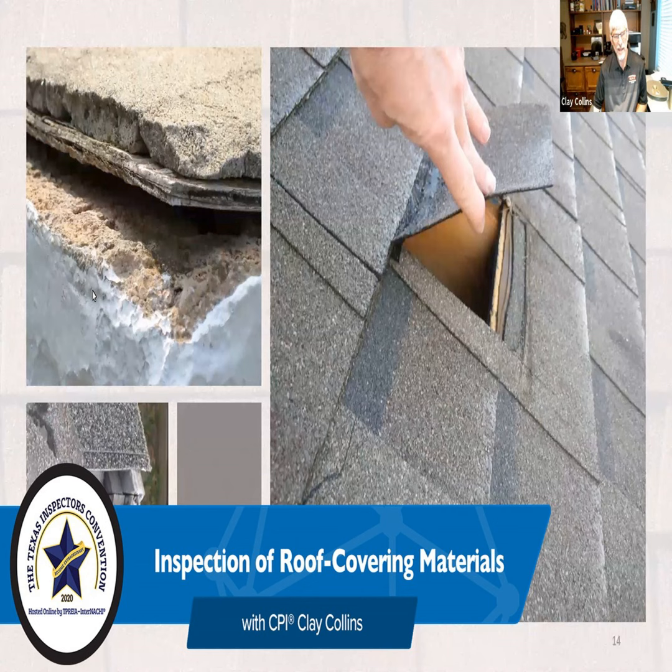Now that's not what I adhere to, because you can walk up a valley easier than you can walk up the field of a roof. You can walk up a hip easier than you can walk up the field of the roof. You can walk by a dormer where you can hold on to the trim and then hold on to the eave of the dormer easier than you can walk up the field of the roof. If it's dry and the roof cover is new, you can walk up the field easier than one that's old and the granules are all loose. But if you want a safe answer, 4/12. I don't think that's necessarily realistic, but that's a safe answer.